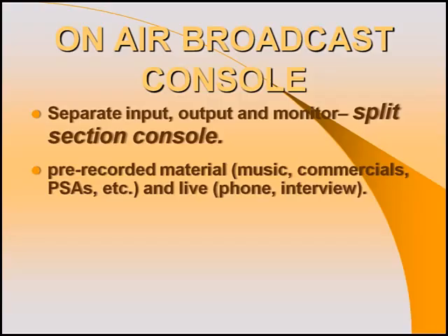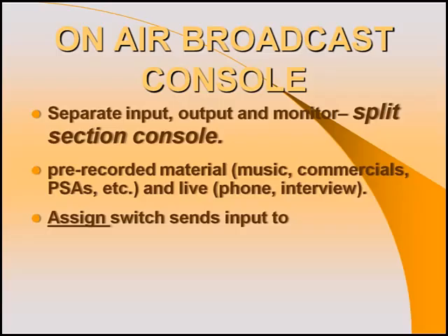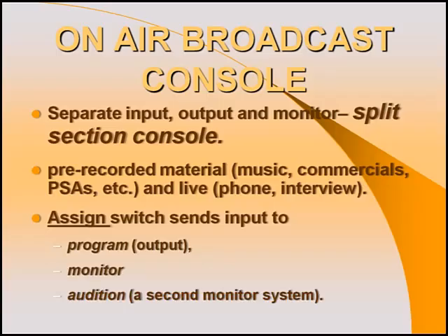Such broadcast consoles provide the ability to assign the input channels to a particular output. If we want the signal to go out on the air, we assign it to the program output. There is always a monitor output where we can listen to the signal, and there is always what is known as an audition output, where we can send the audio signal to another place besides on the air, such as a recording device or another radio studio.